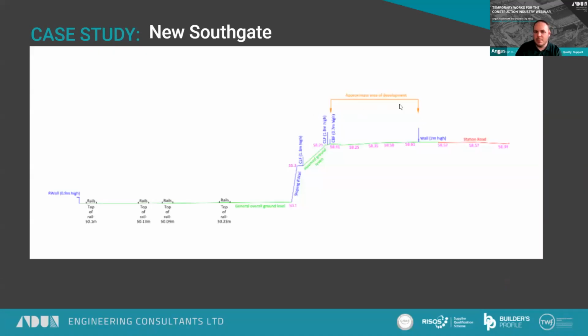So you think, oh, development's up here, and then you start seeing things like assumed ground level, general overall ground level, and then you start thinking to yourself, hang on a minute, we put a retaining wall on here. It's just sketched in roughly, typical dimensions. Quite a significant part of this site is surcharging that wall, and now we're going to run a 50-60 ton piling rig on the site.